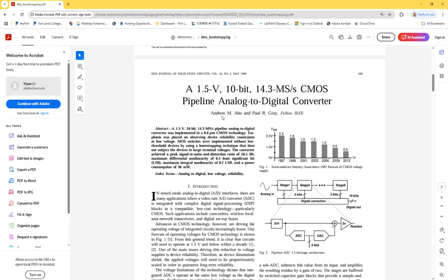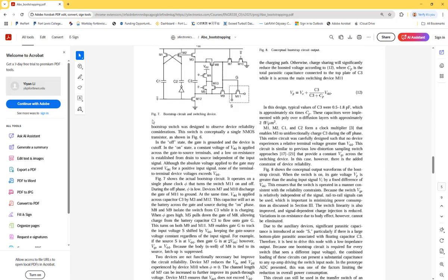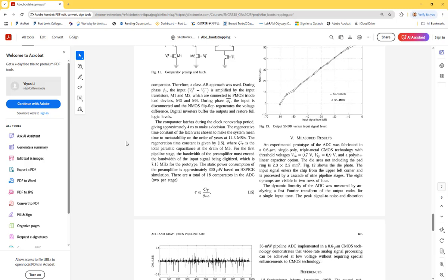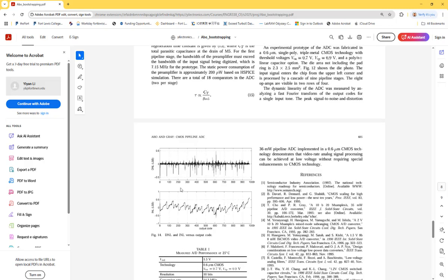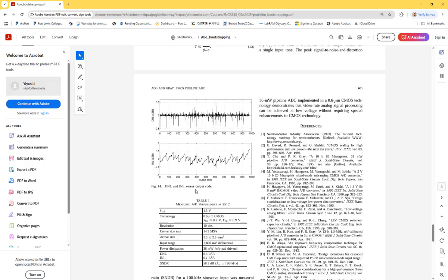So this one is published in there, and if you look at the INL and DNL plotting, how do they plot it? It's in the time domain. Okay, so it's okay to plot in the time domain and look at the maximum DNLs or INLs, and make sure that none of them are more than 1 LSB, because if it's more than 1 LSB, you are getting an incorrect code in your final converted result. So just find the journal article and see how they plotted the parameters for the ADC, and we'll just do the same thing. Very simple.